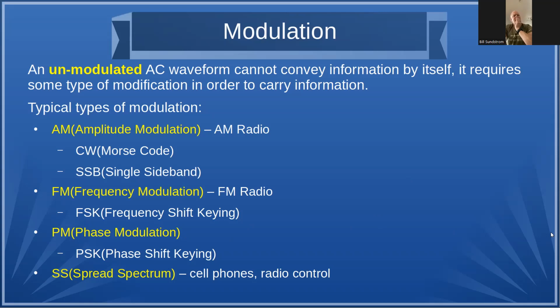I'm just curious, they give examples of AM, FM, and even spread spectrum, but what's a good application of phase modulation for communication? Teletype they used a lot, using multiple channels in the same band, 3 kilohertz bandwidth. They were using phase modulation for each little channel. Oh, okay. That's how Collins came out with that back in the 50s.